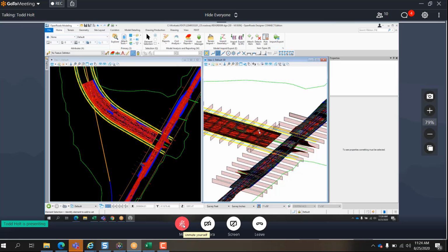So the next step, that's the volumes. Then I can come to the volume reports, and it's going to go off a name boundary. That's why we need to lay them out to the name boundaries, because we should see in here the two different name boundaries. We have one for the State Road 61, so we can compare just off the name boundaries. So let's do the center line of this CL and data point to accept the boundary, and then this is going to select the start cross-section name boundary for volume. So I'm just going to reset to complete.